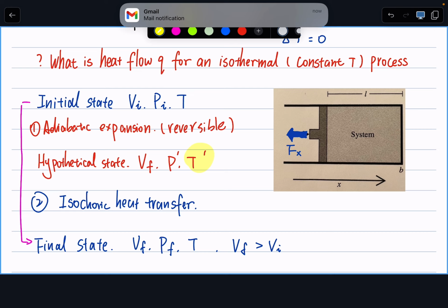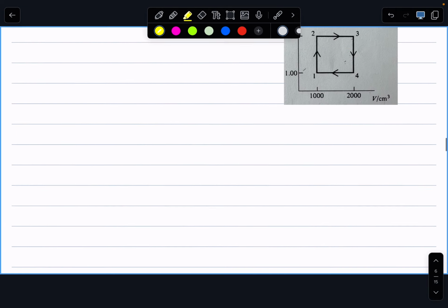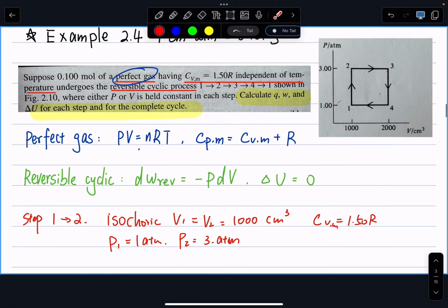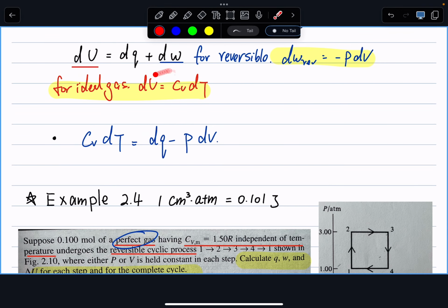Yes? So the definition of Q that you gave us before, like Cp dT, that's only for the Q reversible? Sorry, what's the question? The definition of Q you gave us before, like Q equals Cp dT, does that only apply to no changes of state? Well, the way we put it is for ideal gases. This is the only time we say that dU equals Cv dT or dH equals Cp dT.